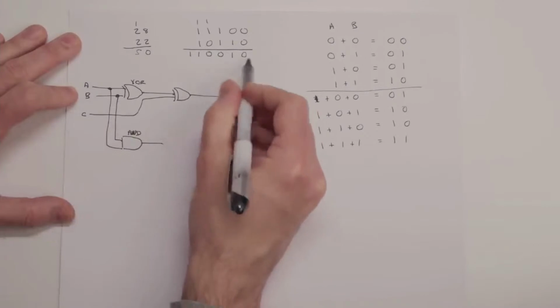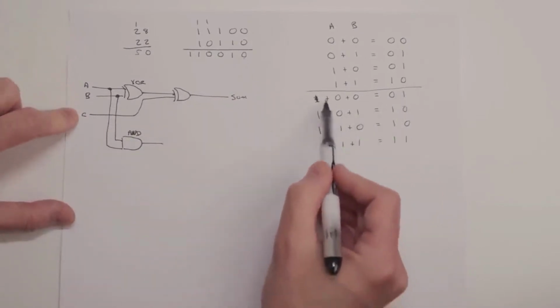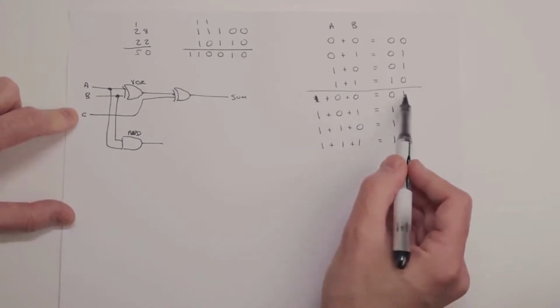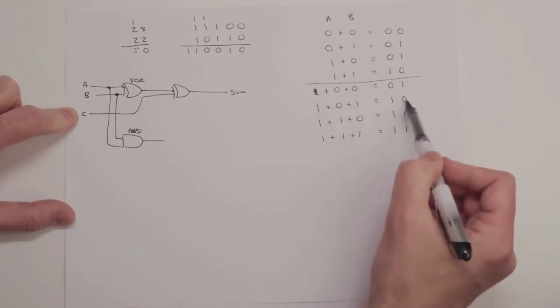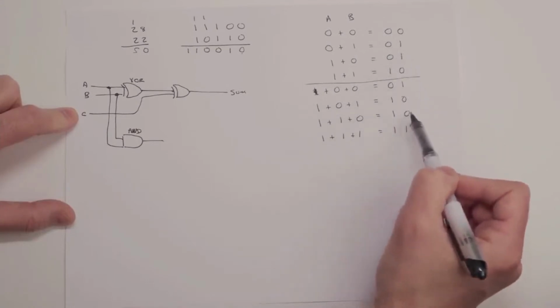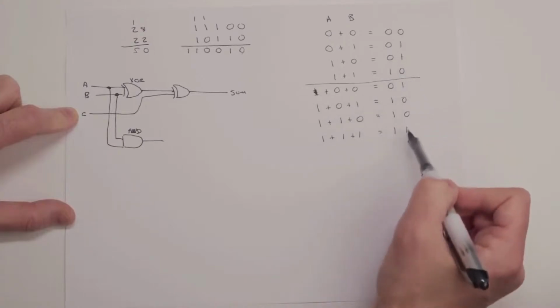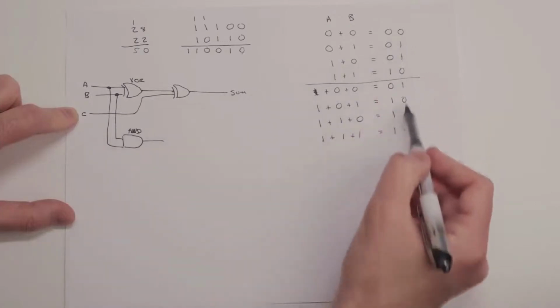And this will be the sum that we put at the bottom here, because what happens is if this is a 1, then a 0 XOR 1 is going to be 1, a 1 XOR a 1 is a 0, a 1 XOR a 1 again is a 0, and then here we have a 0 XOR a 1 is a 1. So this will give us this last column.